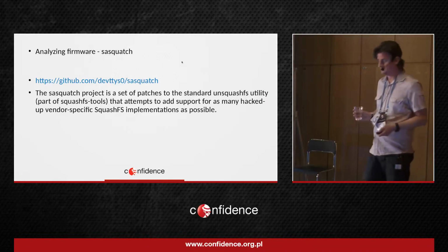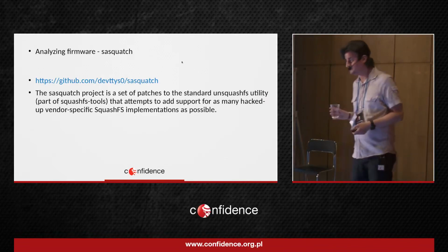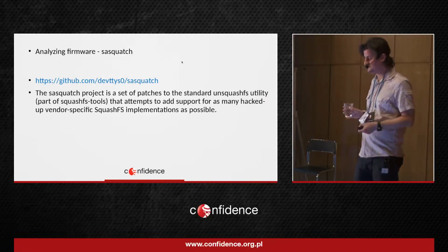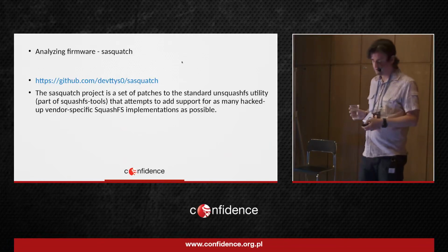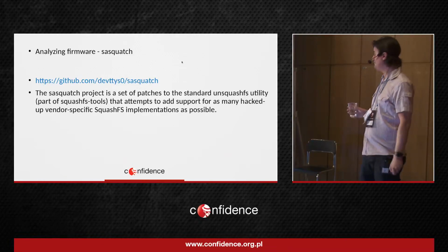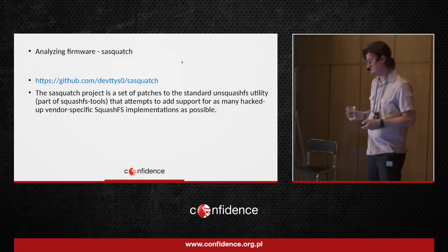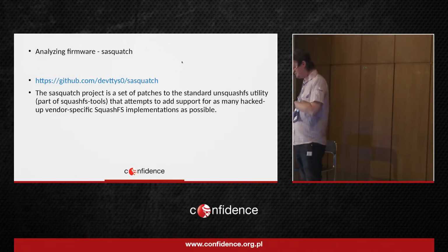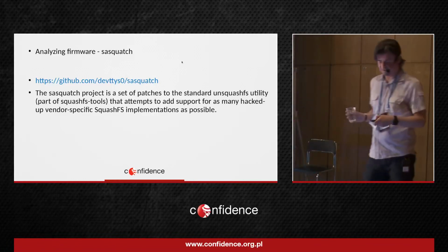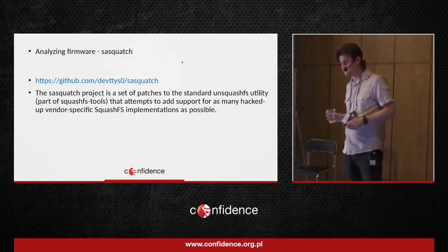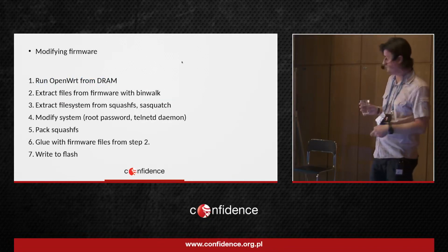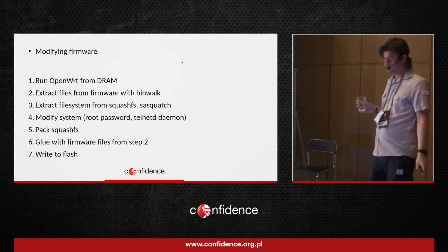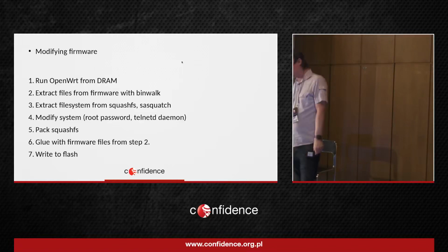There is also another tool, quite older, called FMK, Firmware Modification Kit. In this tool, you can find like 20 or 30 versions of the tools used to pack and unpack firmware files. But I think that Sasquatch is much better because it really could extract files that no other program could. So if your Squashfs doesn't unsquash, use Sasquatch, and it will help. Of course, sometimes you will need to use your hexadecimal editor and by hand analyze and modify the headers of the Squashfs.